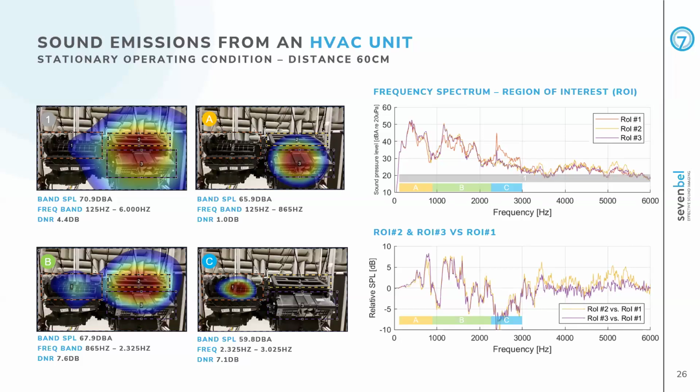kilohertz. That's quite immediate. There are other areas where the yellow curve is higher than the others. If we look around 3,400 hertz or so, we immediately see that the yellow curve is higher than the others, and same from 5 kilohertz and up. And between 1 and 2 kilohertz, we also see that the yellow and purple curves are higher than the orange curve. So now we can start placing filters as we did in the first example, but knowing what to expect.